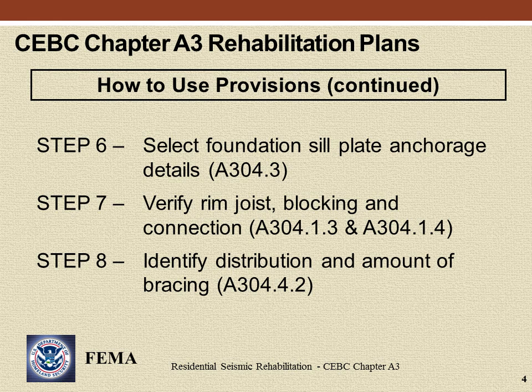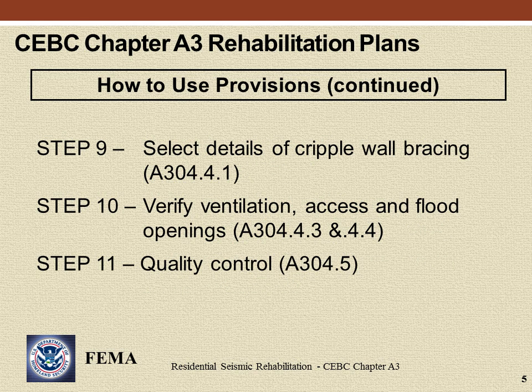Step 8. Identify distribution and amount of bracing. Step 9. Select details of cripple wall bracing. Step 10. Verify ventilation, access, and flood openings. And Step 11. Quality control.